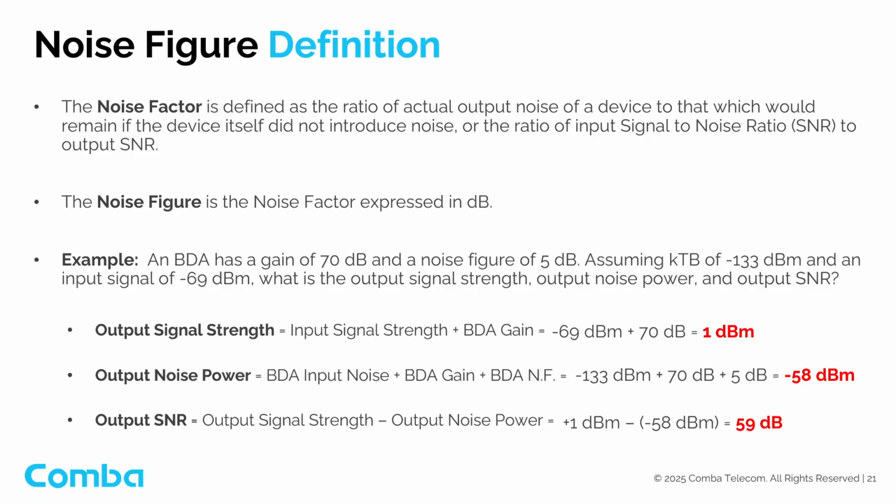Every building has the potential to generate environmental noise from different electrical devices commonly found in buildings. These devices can raise the RF noise floor within the building, potentially leaking into the antenna system and feeding into the BDA. If the environmental noise reaches the uplink input above the thermal noise level, it will be amplified accordingly, and excessive noise output will be present.